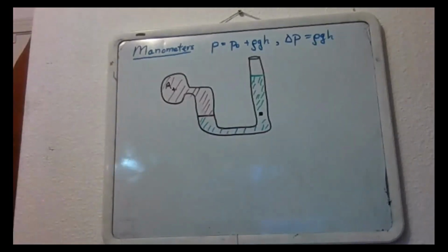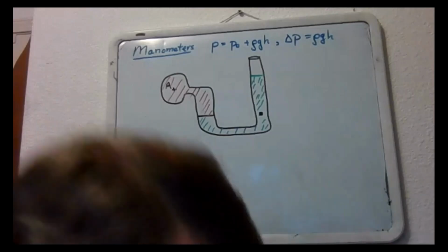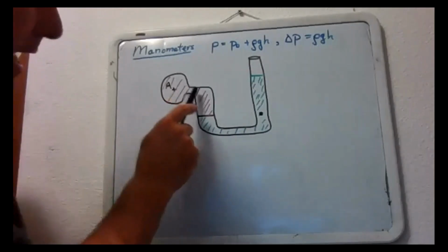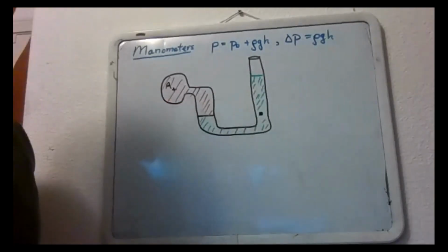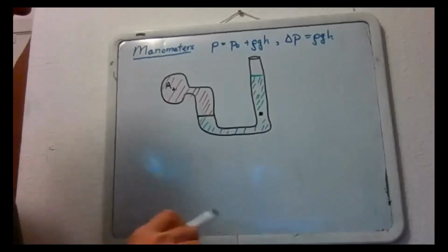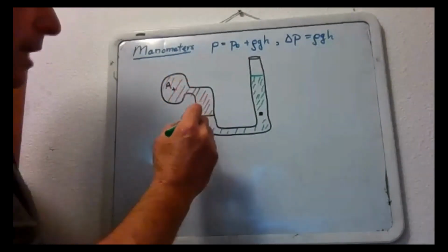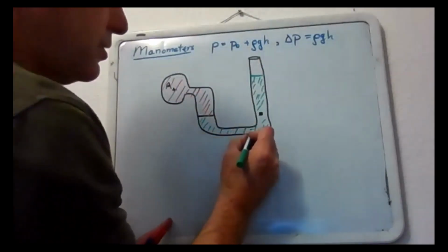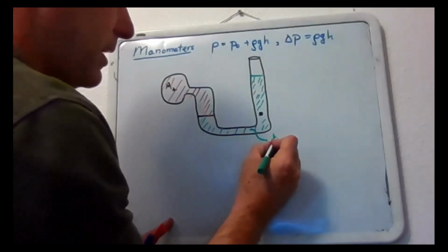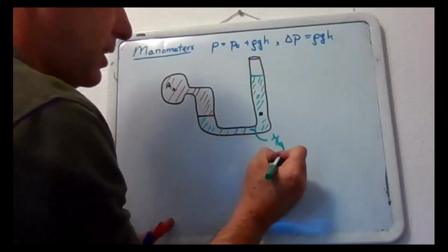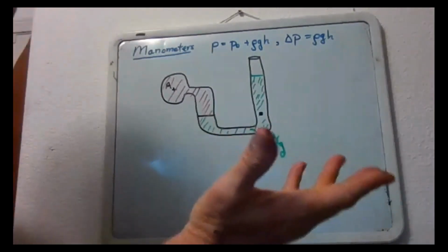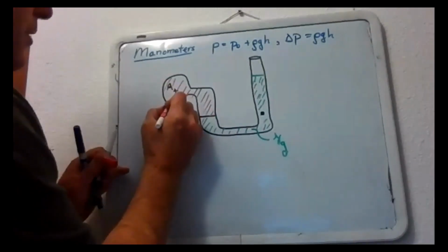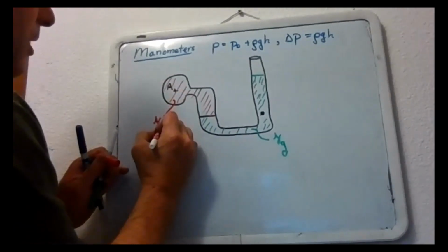So I want to go through that with you guys and see if we can label the various points on there. What they do in the problem in the book, if you want to look at it, is start at A and work their way like that. Let's just say that we have two different fluids here. This is a fluid that's in a container. This is a second fluid, and hopefully you know what's going on up over here. So for argument's sake, let's say that this fluid right here has density gamma sub g. Gamma is its specific weight, actually, and g is for the green fluid, and here I'm going to call this gamma sub r.